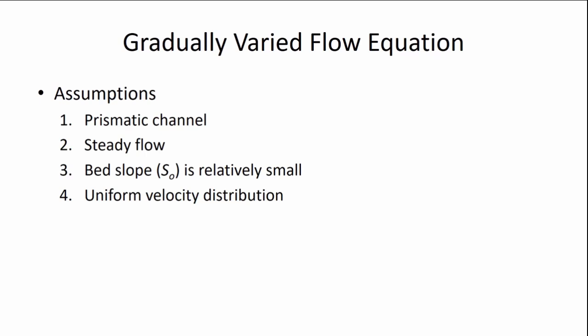That's primarily where errors pop up in predicting what we'll observe in the field versus these equations. This error is maximized for shallow slopes, but when you have a relatively deep slope, the error becomes smaller.